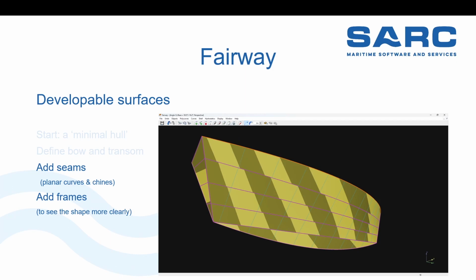This is what you get after interpolating some further frames. And these patches are rendered, let's say, from the outside inward. That's how we define our surfaces in Fairway. And of course, this is a chine, so you will have a discontinuity here, because the frames here would have a little chine there. Not this one, because they were interpolated. Actually, they are hollow here. But the knuckles are not included there yet, because I switched them on as chines later on. Doesn't matter. I fixed all that.